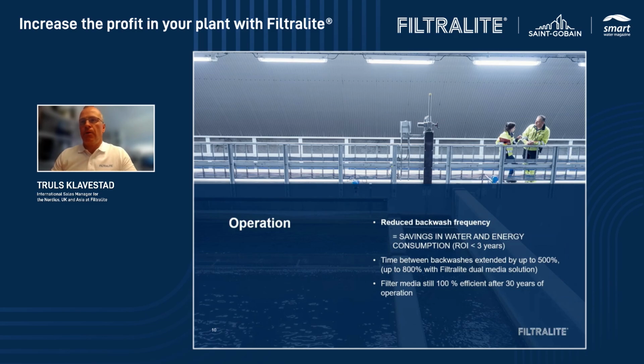So as I said before, it depends on which kind of Filtralite solution you compare. If you compare single layer sand with single layer Filtralite, it can be up to 500%. That means instead of backwash once a day, you backwash every 5th day. And if you take 2 media of Filtralite compared with sand, then it's not every day, but every 8 days. And also the lifetime of the product is very important.